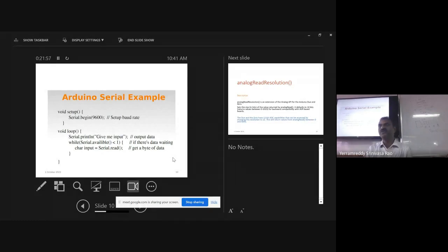Computer CPUs were unable to perform. CPU, I'm talking. CPU doesn't have multiplication and division. Right? In first year in digital electronics, you have a last chapter called 8085 CPU. When you study 8085 CPU, you realize that it doesn't have multiplication and division instructions. So it means that implementing multiplication and division inside the CPU is impossible in 1970s. That's a challenge.